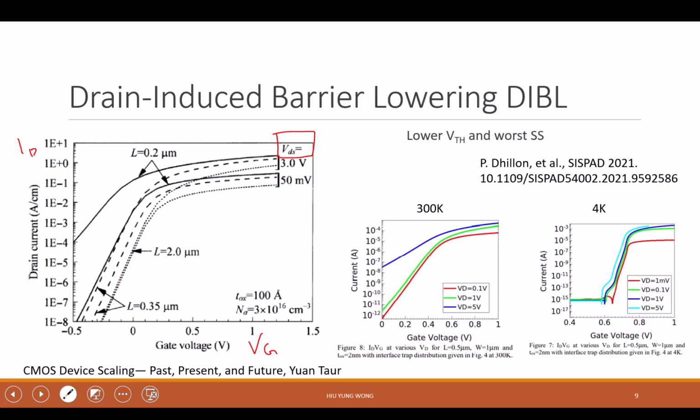Yeah, I've seen some GlobalFoundries publication where they use exactly that method, and they decided, I can't remember the numbers, there was one threshold for PMOS and one for NMOS. It was several hundred nanoamps, but I never understood where they came up with those numbers as to what that threshold on the y-axis is. Yeah, I also don't know how they pick it. But again, I feel that it really doesn't matter in all the analysis, even if you change it.